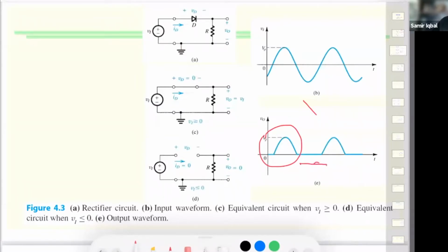So you see this part, there is no current conducting through there. If you apply what we just discussed on the previous slide, in forward bias you can show it as a short circuit, just behaving like a resistance of 0 ohms, which means no voltage drop across it.